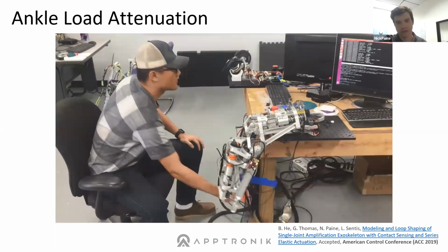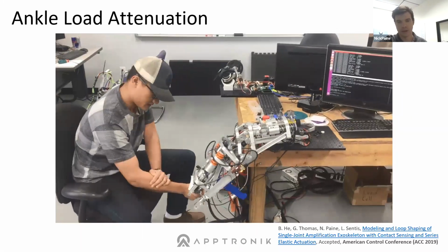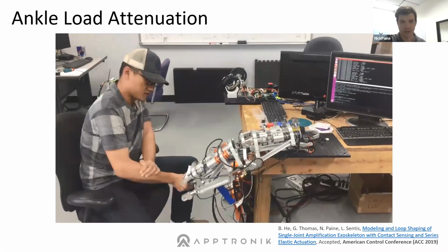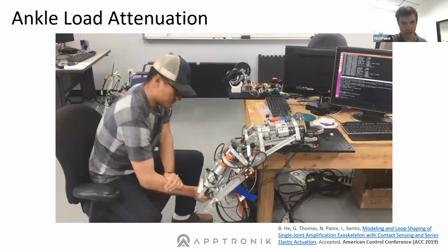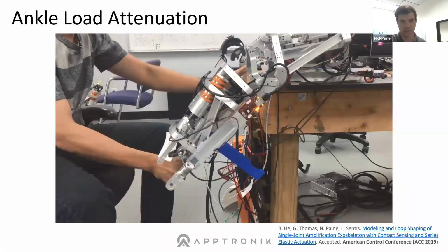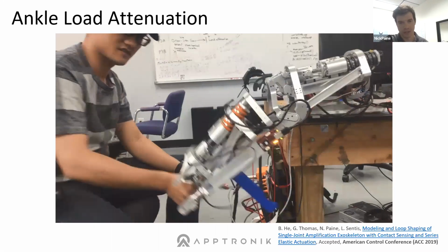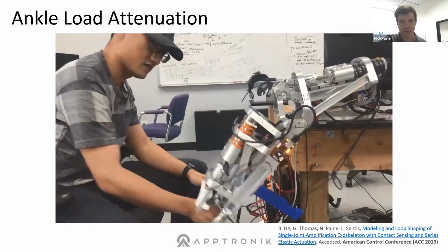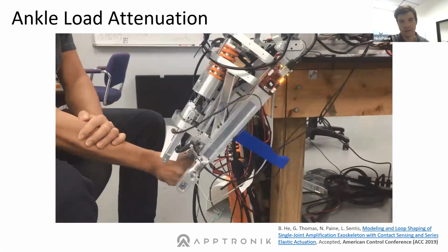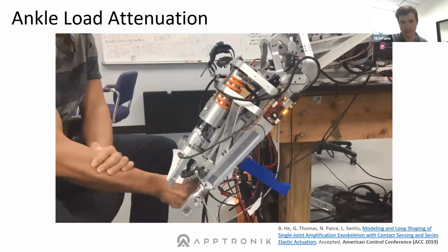And by that, I mean, when you have a system inside of an exoskeleton and you're trying to control interaction forces, the human's dynamics, their muscles, their skin are inside the feedback loop. And so trying to design robust feedback controllers for the various impedances that the human can have is a challenge. The human can change their impedance by co-contracting and different ways like that. So there's some work that went into this to make the feedback control relatively insensitive to those plant dynamics of the human.